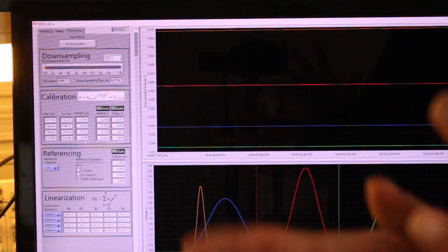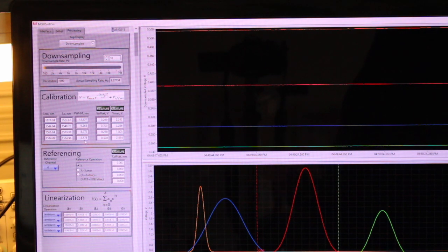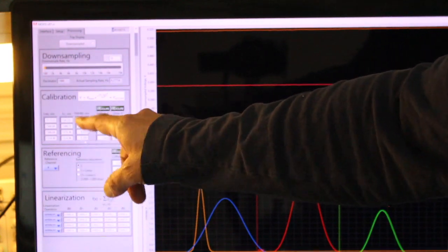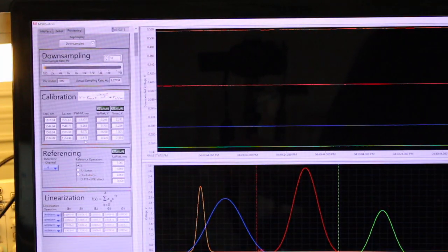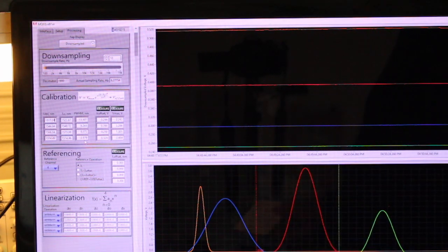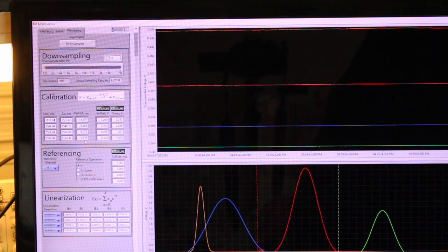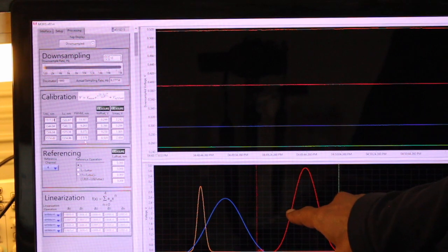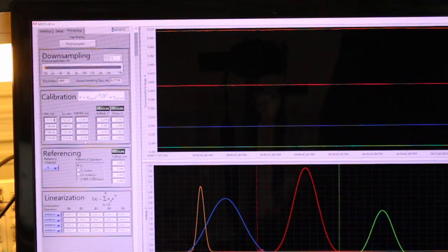So the next thing, once these parameters are entered, which are usually given within the measurement report of the system: in the measurement report, we provide the center wavelength of the WDM filters. We provide the full width half maximum of the WDM filters. And the user has the information for the fiber Bragg grating array that they purchased or the one that we provided. In the measurement report, there will be a column that will tell the user the optimum wavelength of the fiber Bragg gratings to use. And the optimal wavelength will occur at the 3 dB point of the WDM filter. Okay, so we have that.